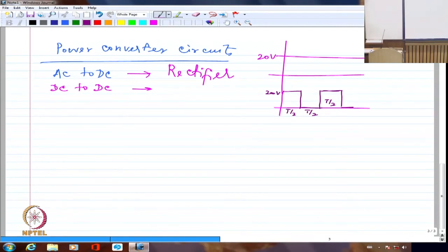It's going to take a while for the motor to realize that, okay, I have to pick up speed quickly because they have given me 20 volts. And they have not given me any voltage, let me just come down to 0 speed. It's not going to happen, because the inertia is going to take a while before the motor really responds to the variation in the voltage. Because of which the average value seems to be 10 volts.